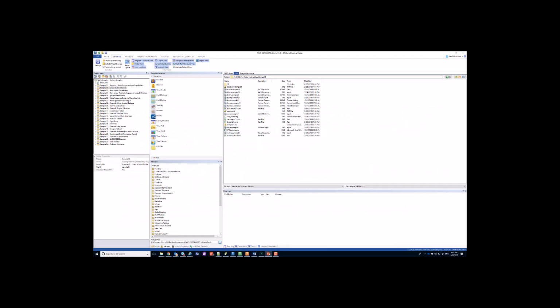I'm going to go ahead and jump into this example that I've created for you guys. I'm going to look at a few things real quick first before we look at the wind turbine job creator. So when you're doing it, you're going to need some, I kind of think of them as partial input. If you're familiar with doing fatigue analyses, we have a partial fatigue input file that can then have different information added to it depending on the analysis. The same kind of principle here is we're going to be providing some partial input, and then that input is going to be filled out with all of the information that we put into the wind turbine job creator.